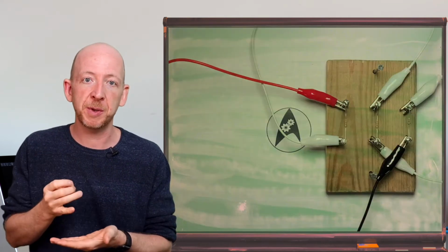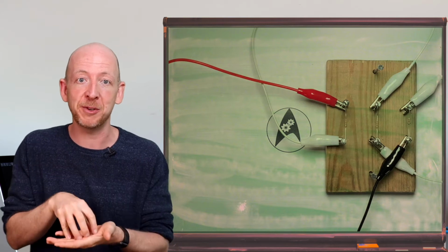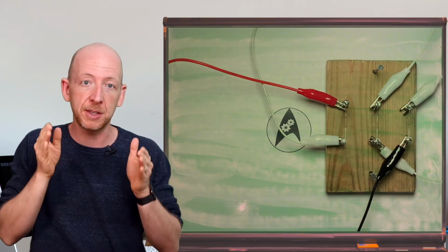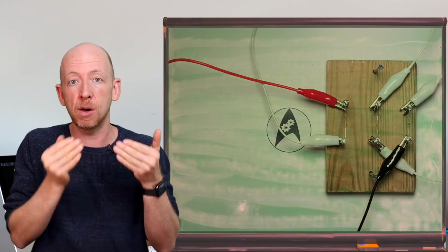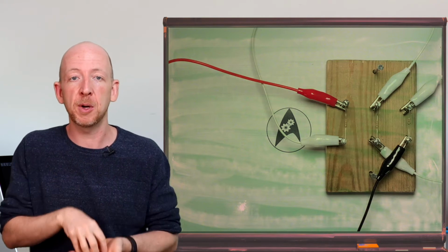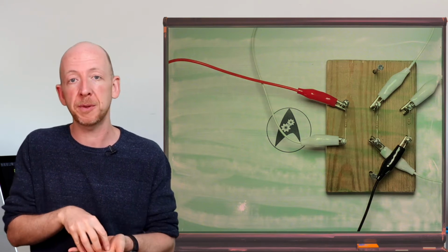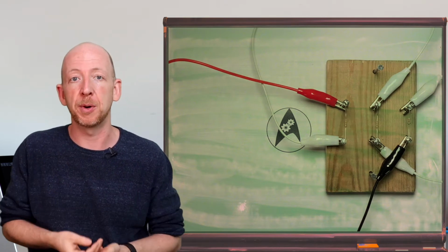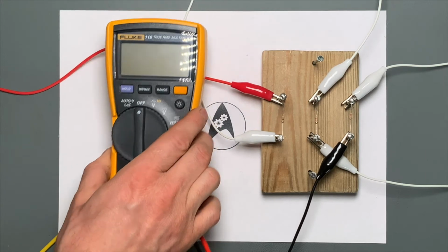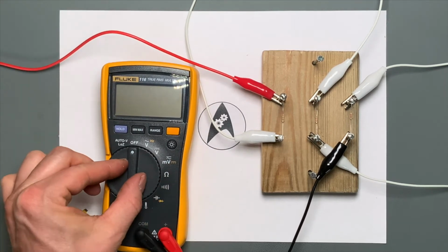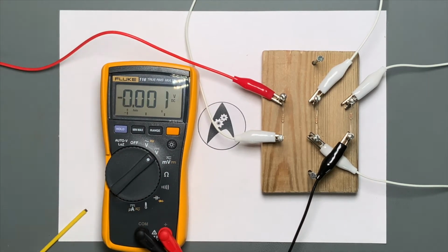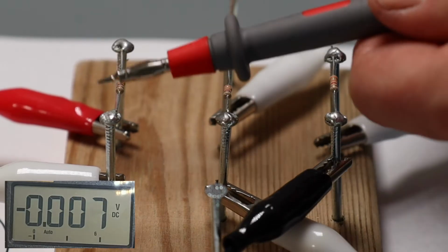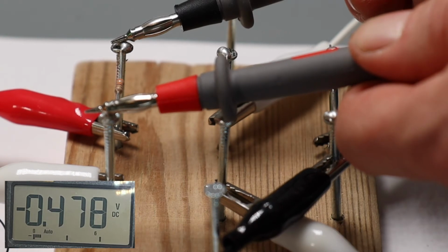And in the next measurement we will now focus on the voltage, and we will measure it 4 times now across each individual resistor and across all resistors combined. And for this purpose the ammeter has been removed from the circuit again, so that the measurement is not being changed by an additional component here. And so in order to measure the voltage drop across the resistors, we now switch the multimeter to DC voltage measurement, and then we press the 2 test probes firmly onto the upper and lower ends of the left resistor to measure the first voltage.